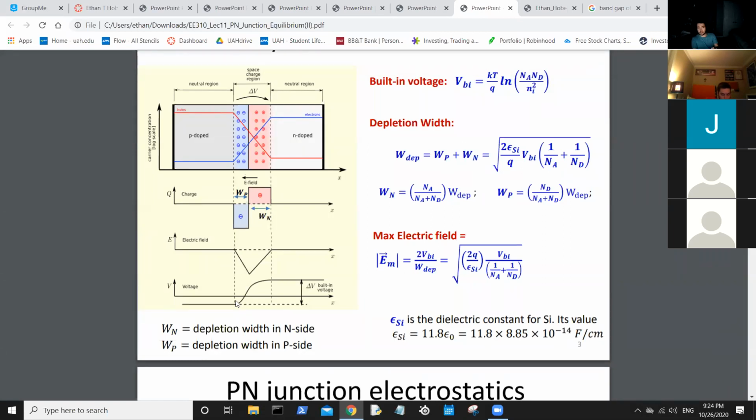We just need the ratio of the width. Because overall, the width of this whole thing is, for the purposes of this math, 1. And we only need to calculate the ratio, or how much of that 100% is taken up by the P or the N side. We calculated in our question that P is less doped. N is doped twice as much, like 2 times Na. So using that, you calculate the P value, and we came out with 2Na over 3Na, cross out your Nas, is going to be 2 over 3.